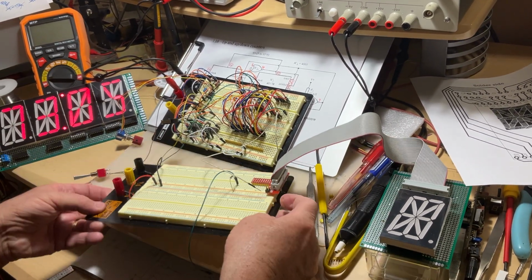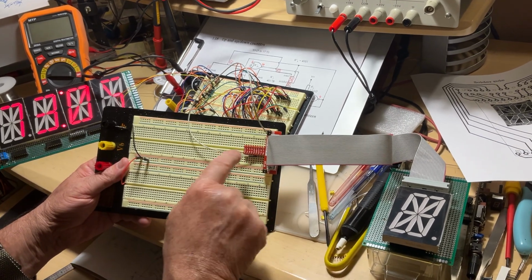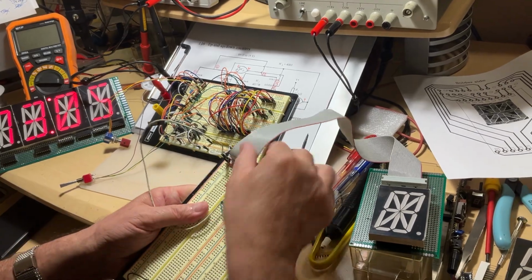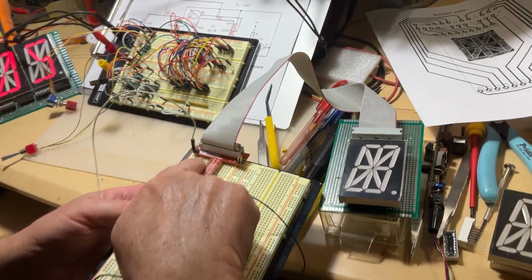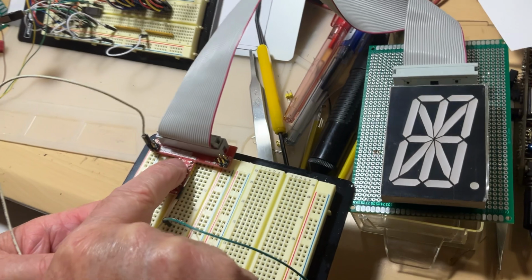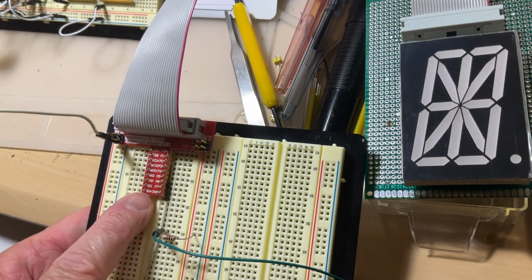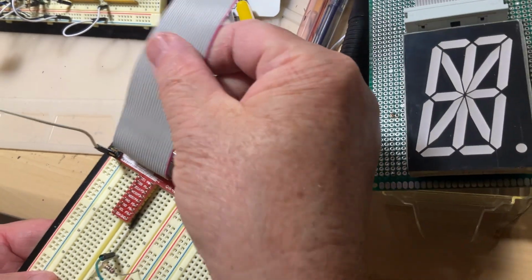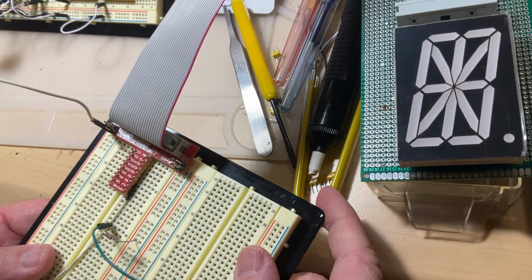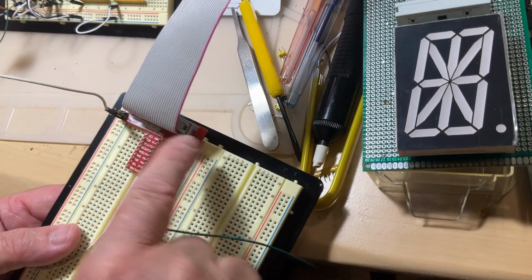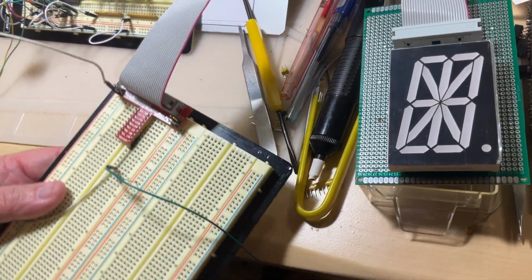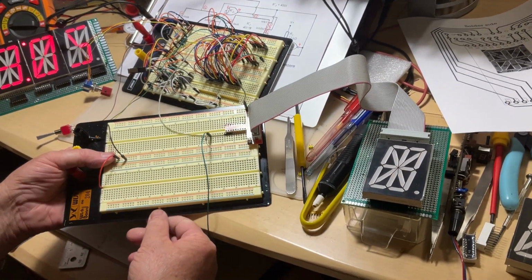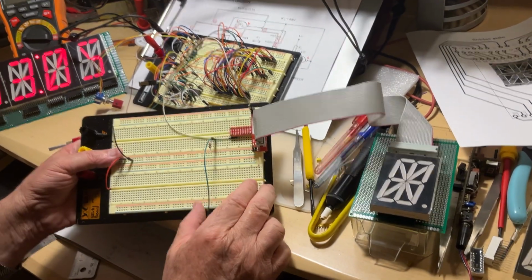Be careful because what you have to respect is the little cobbler here. And by the way, what I'm going to describe is an extension board for a Raspberry Pi, for the Raspberry versions A and B, with 26 pins, the flat cable, and the GPIO, the old version with 26 pins. Surely we can use the newer one, but the newer one is 40 pin, is too bulky, too big, okay?